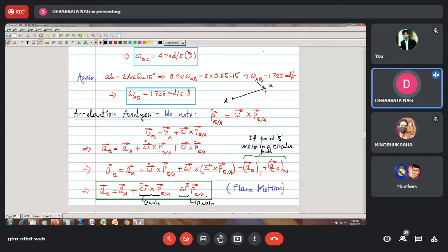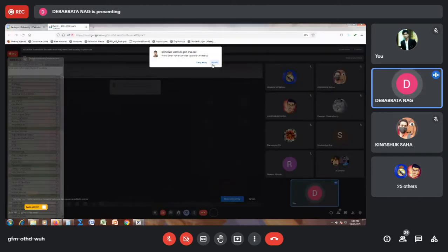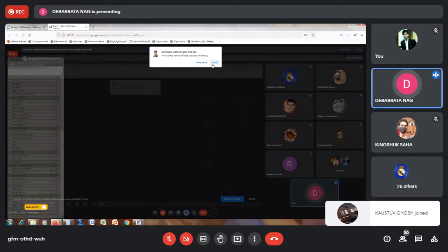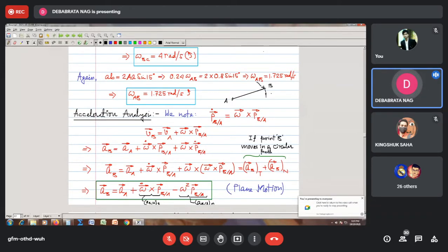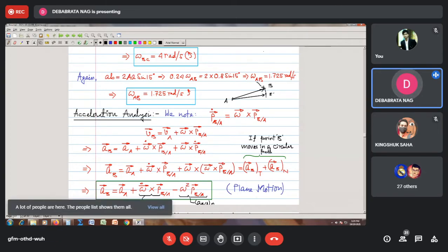So as a result, the magnitude of this vector is not going to change. The only thing that is going to change is its direction as the point B changes its location, say it comes to B prime. So obviously the vector comes here. The magnitude of this vector and the magnitude of this vector will be the same because both of them represent the distance between the two points, and from the rigidity definition this is going to be constant. There is no change in magnitude, but we do have a change in direction.